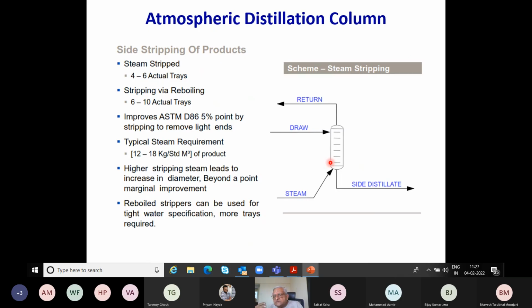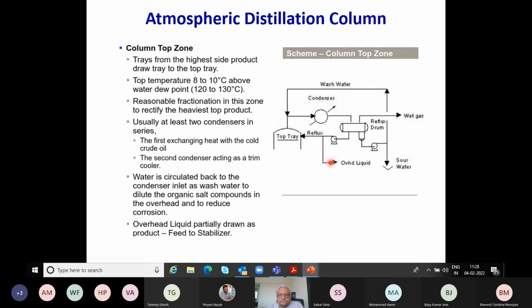This is not acceptable; there's a test called water separometer index, and it doesn't meet that particular quality. It can create problems in the aircraft because that water can form ice and choke the nozzles in the jet engine.